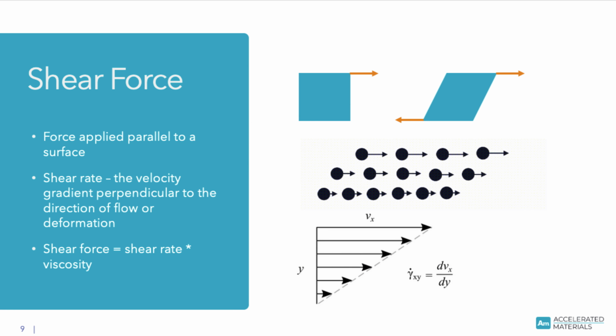Shear force is another very important thing that you need to consider when you are making scaled nanoparticles. And for those who don't know, shear force is basically a force that's applied parallel to a surface of an object. And it's defined mathematically as the velocity gradient perpendicular to the direction of flow within, let's say, a fluid motion. And so you can see through this little animation here, when you have particles in flow, that shear rate is proportional to that velocity gradient from the top to the bottom.